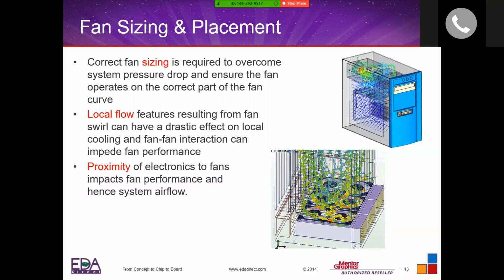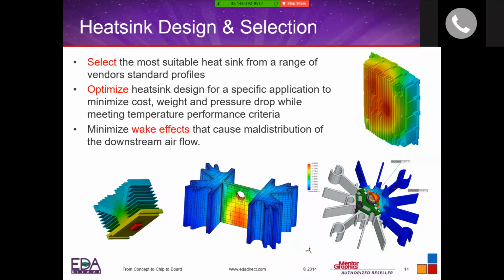You might not be designing the chassis, but you're looking at implementing the fan. You might be looking at designing a custom heatsink for your particular board, particular chip that has a very specific requirement where it will dictate a custom heatsink design. And here's the problem statement with the heatsink: when you first power on the system, it is cold, and so the airflow will be different.